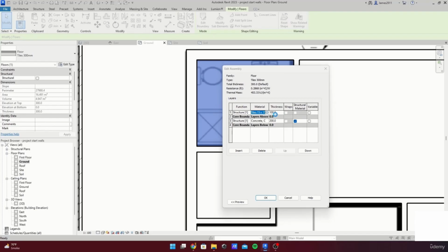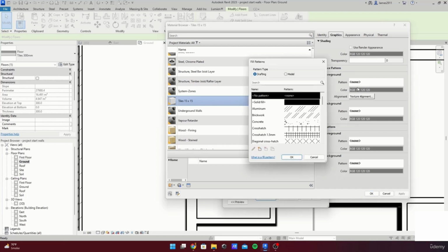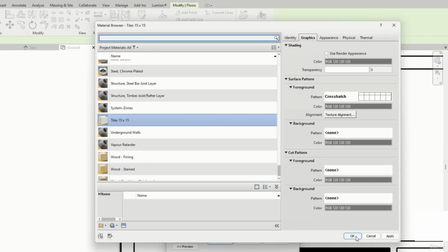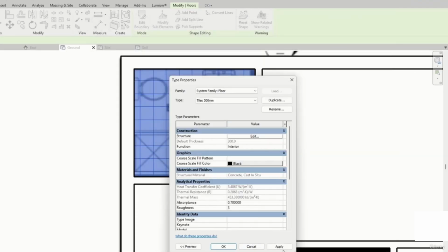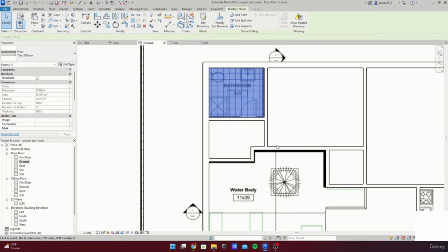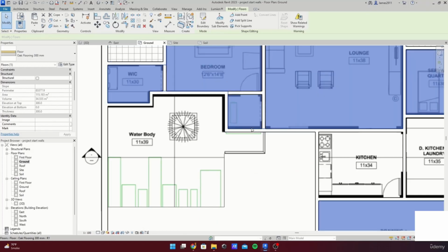The way you'll select the floor is just by navigating to a wall near the floor that you know you have. Well, now actually don't click. Just pan over the wall and click Tab, Tab again, and the blue outline will appear on the floor. Highlight and click on it. Now my tile floor is selected.